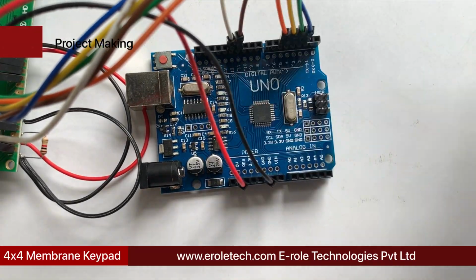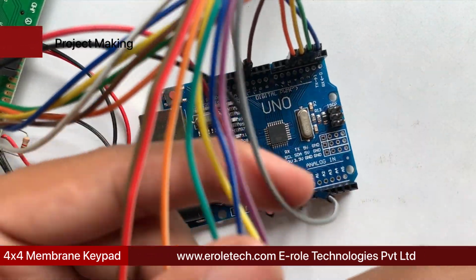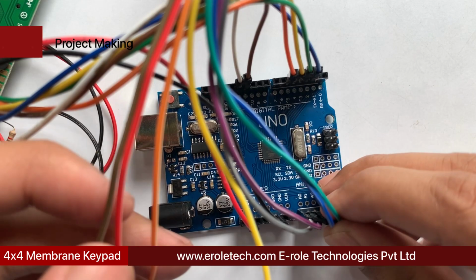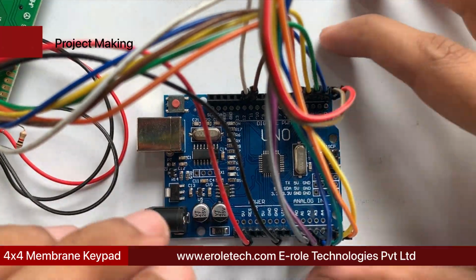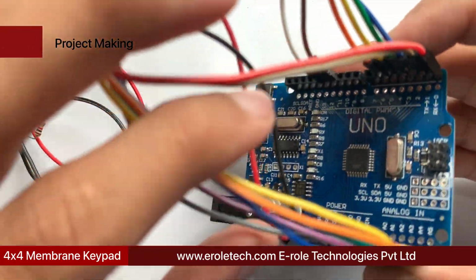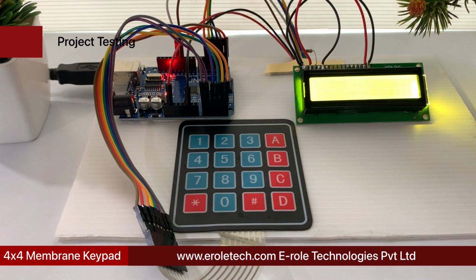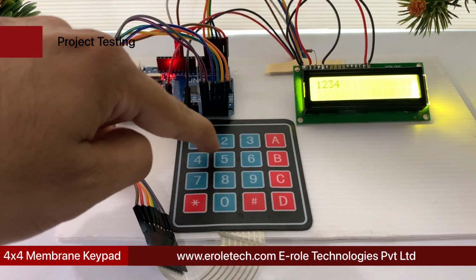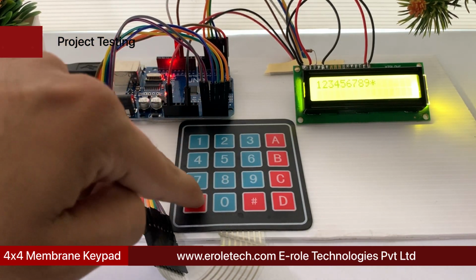of Arduino respectively. Connect the gray wire of the keypad with pin A0 of Arduino, purple wire with pin A1, blue wire with pin A2, green wire with pin A3, yellow wire with pin A4, orange wire with pin A5, red wire with pin 0, and brown wire of the keypad with pin number 1 of Arduino. Now we will power up our circuit and test its functionality. We can see, as we are pressing the keys on the keypad, Arduino is printing the same on the LCD display.